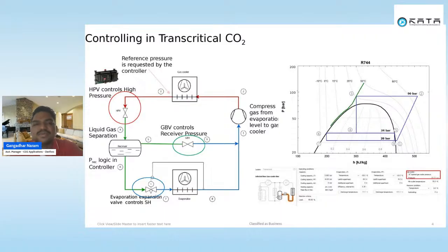So this is a simple standard cycle for CO2 applications. Here we have the compressor, gas cooler, high pressure expansion valve, flash gas bypass valve, receiver, electronic expansion valve, and evaporator. All of this needs to be controlled through one controller, which we can call a high pressure or AK-PC controller, the Adap-Cool pack controller.